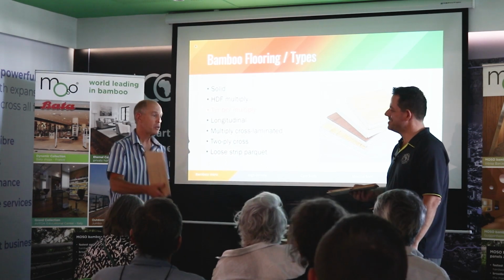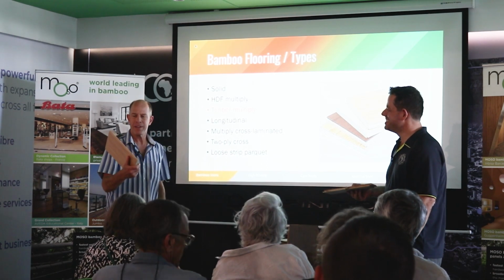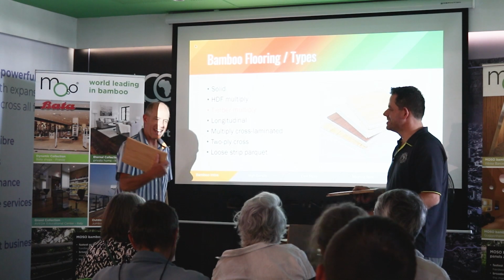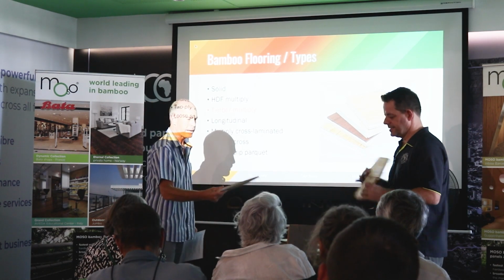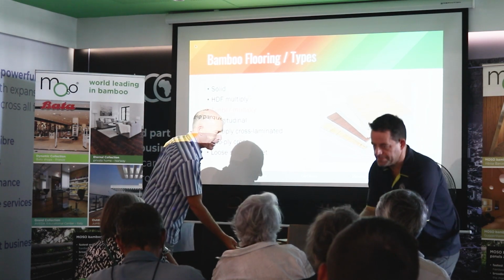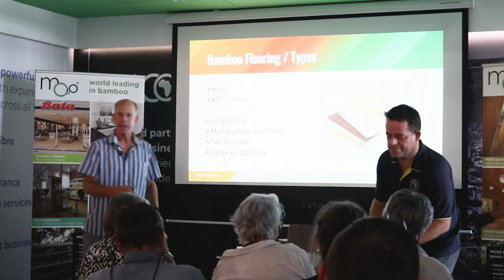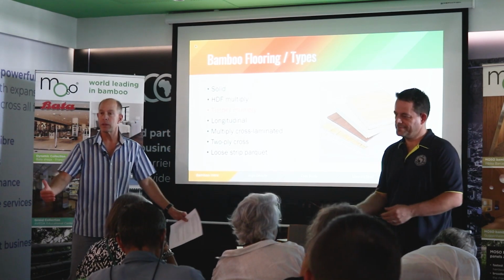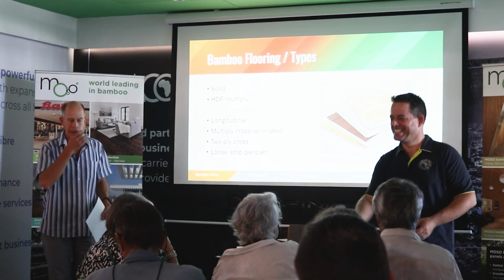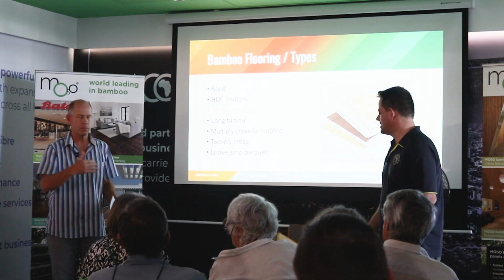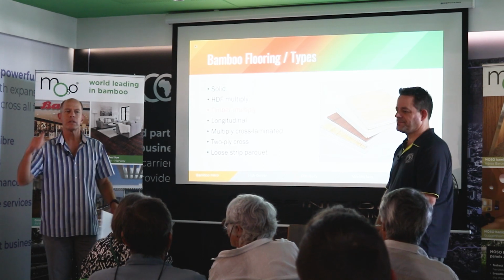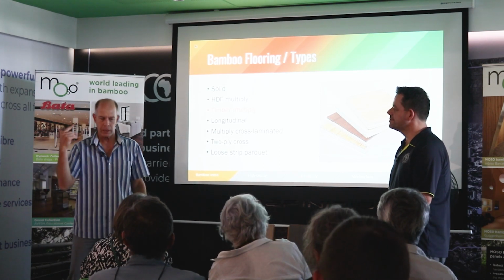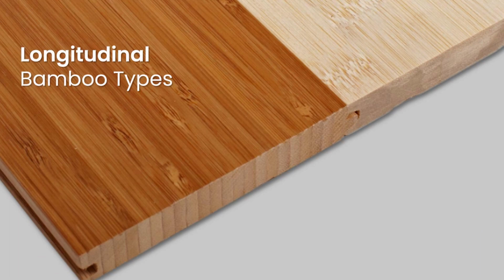Okay, so yes, the main advantages of the engineered plywood-backed flooring is lower cost than solid and higher stability, which means you can increase width, as Barry says. And again, depending upon the particular product and the particular application, it can be installed floating, glued down, or on joists. Okay, next we go on to longitudinal bamboo flooring.